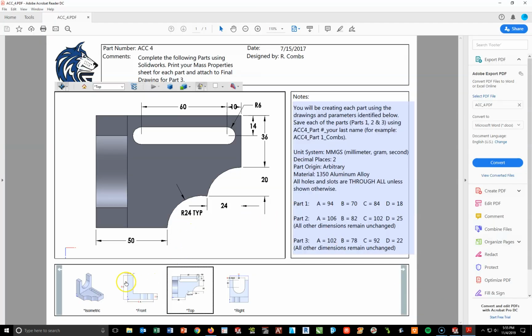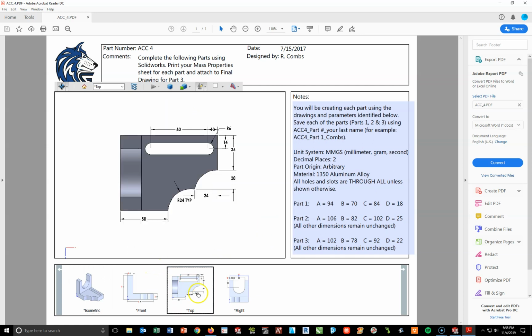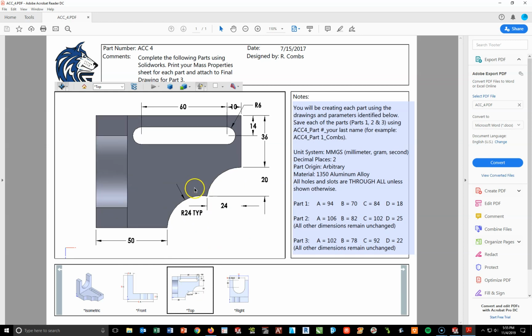Going back to my PDF file now, basically at this point, I've got my L shape, I've got the U cut, and I've got the slot cut. The next thing I need to do is create these two cuts here. Now I'm going to do these with basically 2 circles, looking at the top view. I'm going to draw a circle here and another circle here, add the dimensions that will define those circles, and then do some trimming to get to the little points I need.